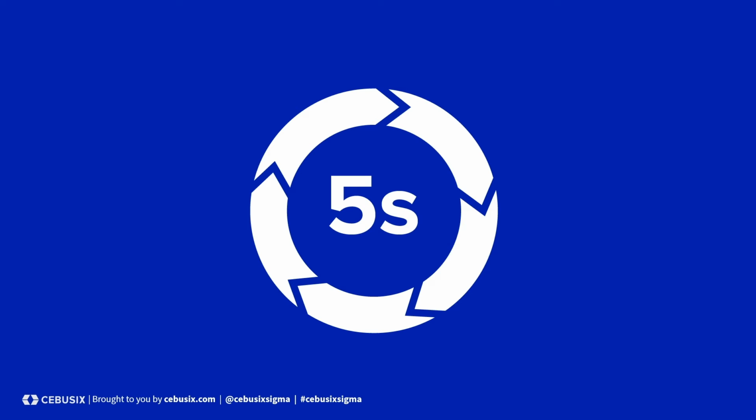The pillars of 5S are simple to learn and important to implement. Sort through all items in a location and remove all unnecessary items from that location. Set in order by putting all necessary items in the optimal place for fulfilling their function in the workplace. Shine the area by sweeping or cleaning and inspecting the workplace, tools and machinery on a regular basis. Standardize the process used to sort, order, and clean the workplace, and sustain the developed processes by self discipline of workers.